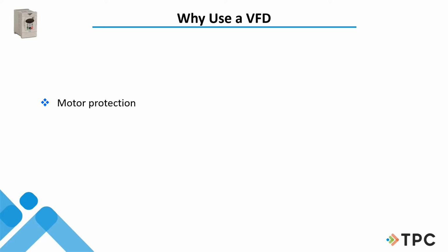I don't have to burn belts off and things. I can say, whoa, I'm drawing way too much current here, and I'm going to shut it down. So I don't have to wait for the overload. So we have a couple of different ways to protect our motor. Also, it will protect it by looking at the voltage from phase to phase and current phase to phase. So a lot of different ways we can do that across the line motor starters can't.